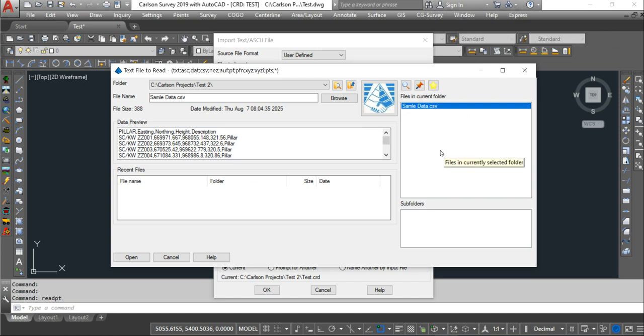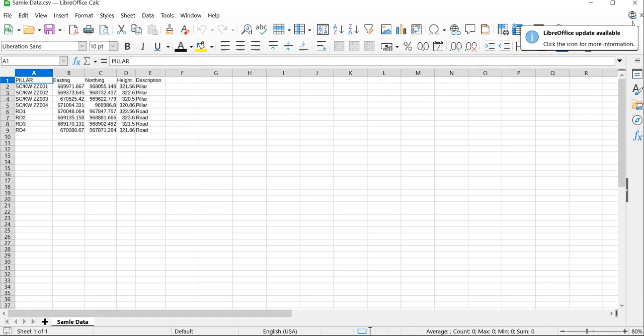So before you do anything, you need to see your data format, and by checking it, you look at your pillar, your easting, northing, height, description. So it all depends on how you want to format it. Please, when you are trying to upload onto your Carlson, let the last number be a digital number like 1 2 3 4. Don't put maybe ZZAH, because Carlson is going to reject it, or is going to make everything a single file. So just ensure that it is in the format.